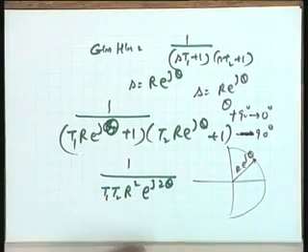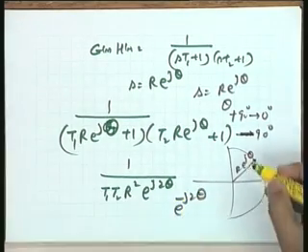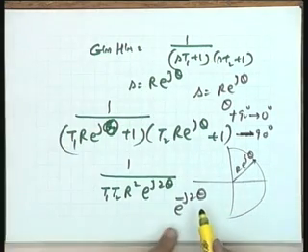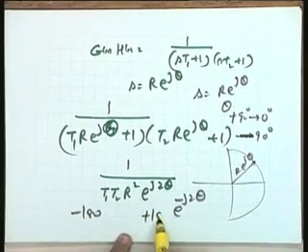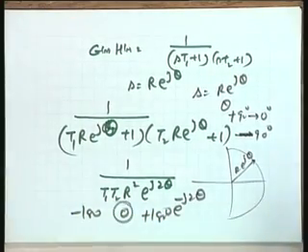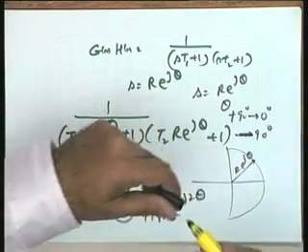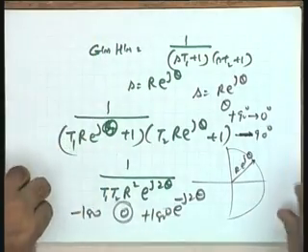And what is this function now? The magnitude is 0, and how about angle? Angle is e to the power of minus j theta multiplied accordingly. So, now you see that as far as the map is concerned, the magnitude is 0, but the angle varies from minus 180 degrees to plus 180 degrees through 0 degrees. I need your attention here, minus 180 degrees to plus 180 degrees through 0 degrees, and the magnitude tends to 0. Now, help me, how can I make this sketch? I think I can go back to this particular plot. How can I make this sketch?